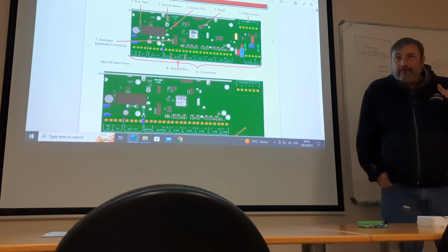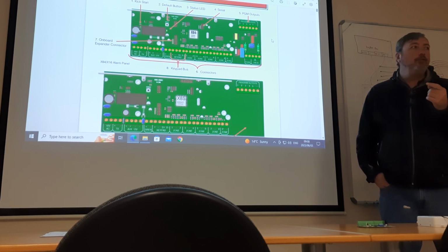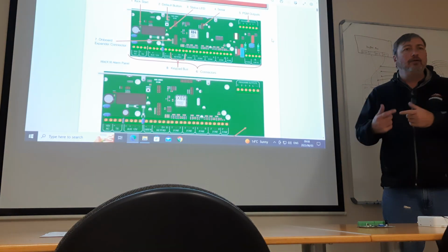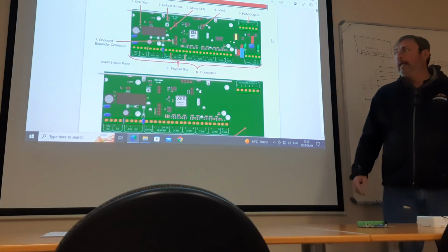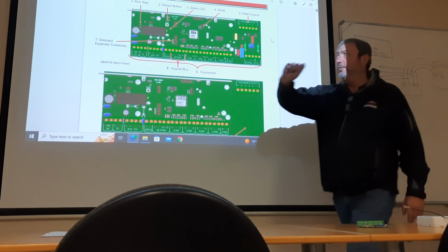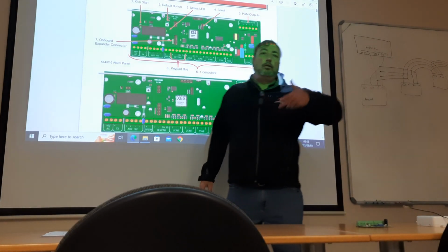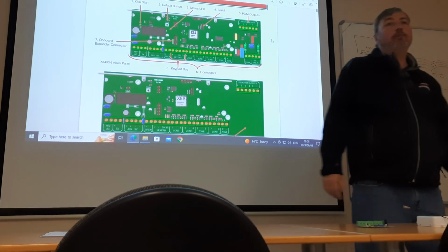To protect the battery from getting damaged, it switches off at 10.6. But let's say you're in a bit of a problem area here and you need to get that panel up, even if it's a little bit below 10.6, just maybe to disarm something. Then you can take a jumper and put it over the kickstart. Then you will be able to run it from the panel.